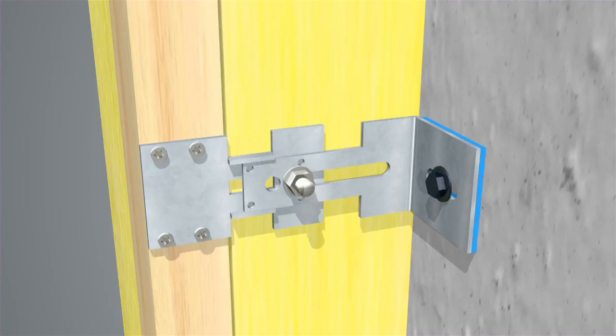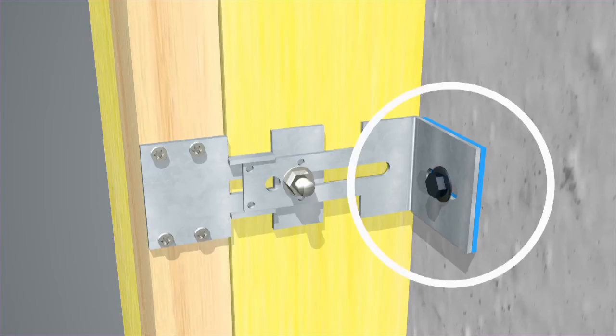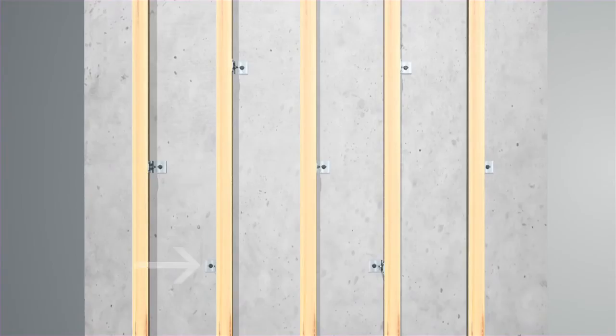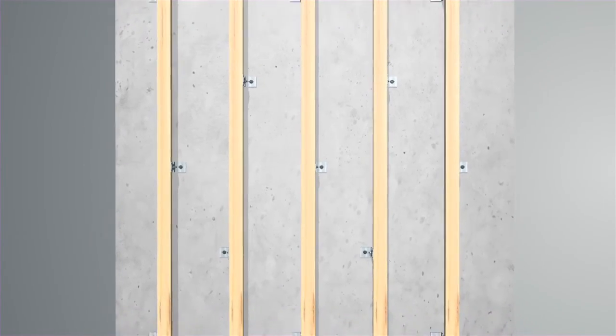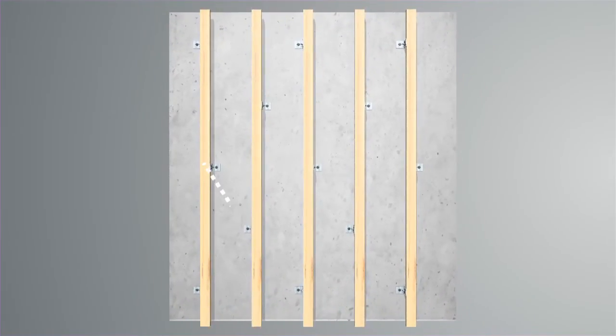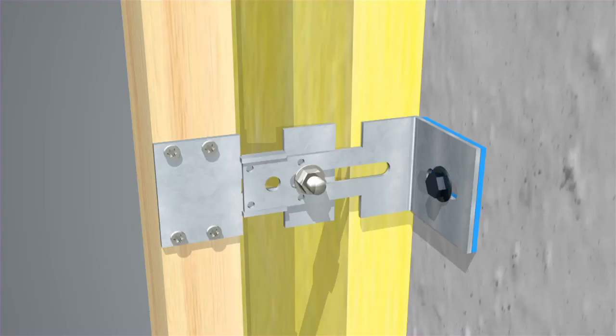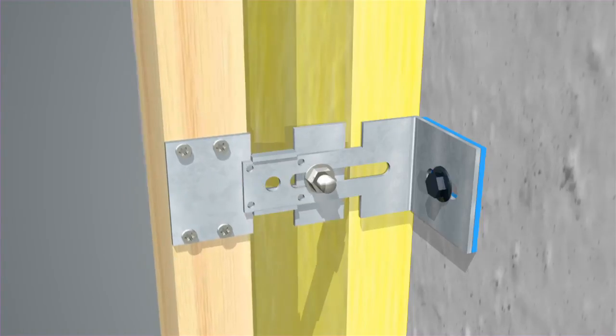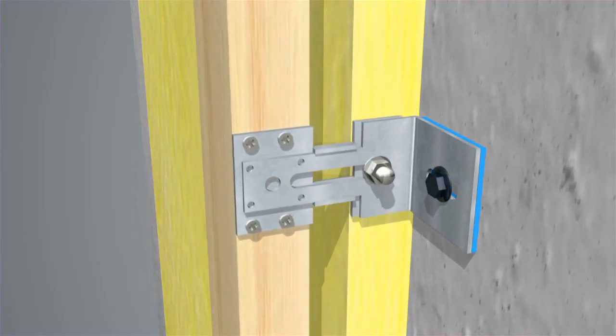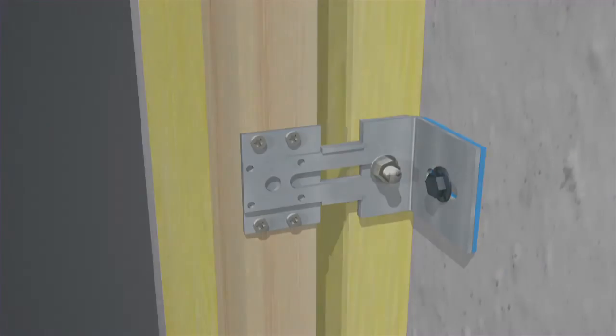The bracket with its thermostop is fixed to the wall with suitable bolts or screws. The brackets alternate to the left and right of the batten to ensure stability. Brackets for neighbouring battens are also staggered horizontally. 50mm thick battens are held in place with 4 stainless steel wood screws. Any levelling can be made before final tightening of the bracket bolt.